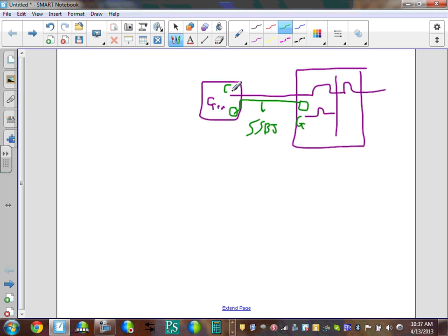So you're paralleling switchgear typically like this. And now, if you have a neutral, here's my neutral. So if you bond the two together here, this is a ground. If you bond the two together, and of course you also have to take this one to the ground too, the ground bar inside your building typically here.